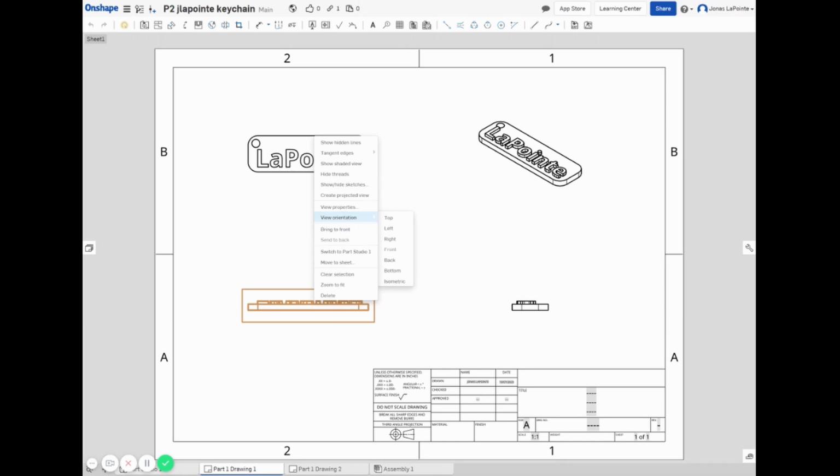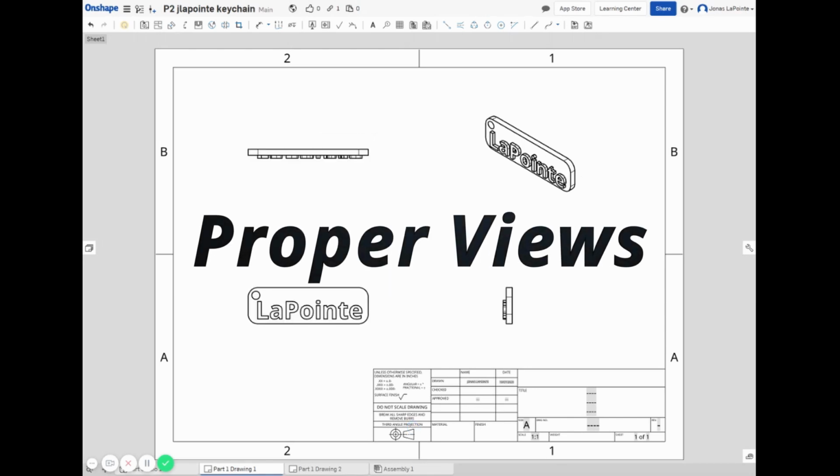If you created this object in the top plane, then you'd click top. If you selected, when you made it, to be on the front plane, you'd click front. So I'm going to select top to rotate mine, and the rest of the images will all rotate automatically.